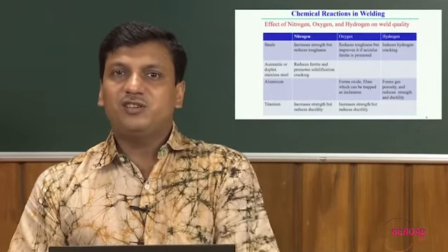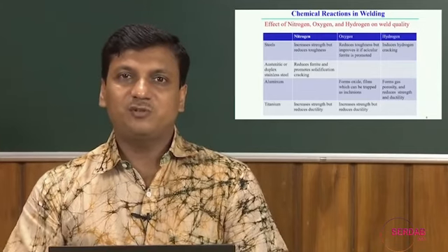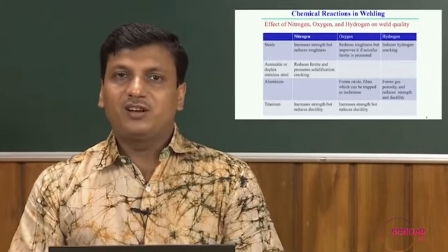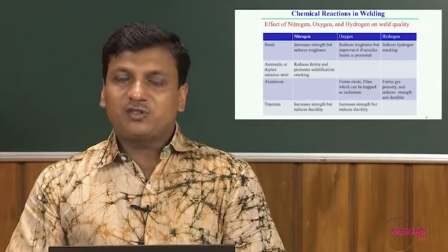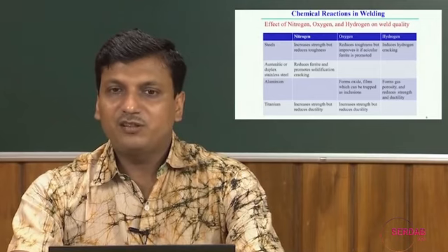Therefore, in welding of aluminum, contact with oxygen is better always avoided, because oxygen has a high affinity to react with aluminum specifically, and this affinity increases with temperature, so it forms oxides. So, that is one serious problem in welding of aluminum, making aluminum oxide.